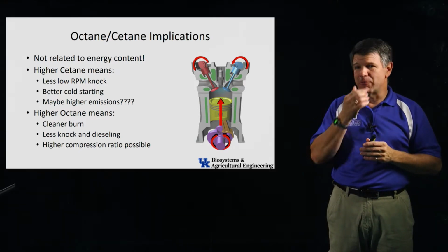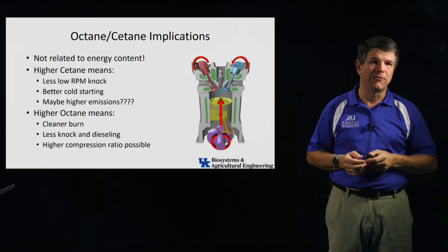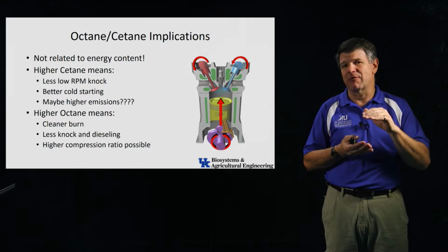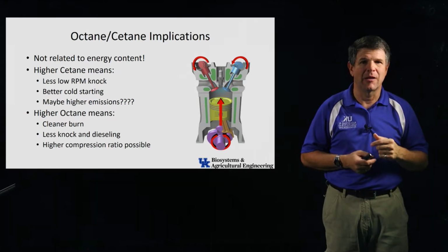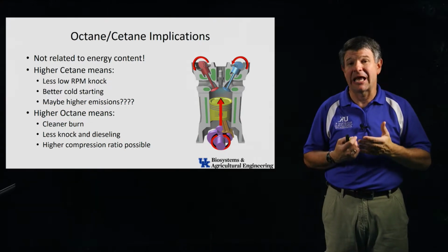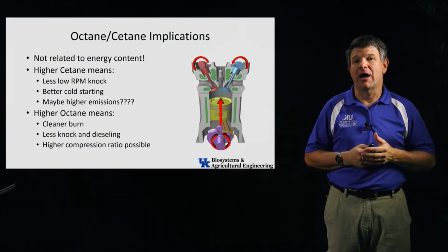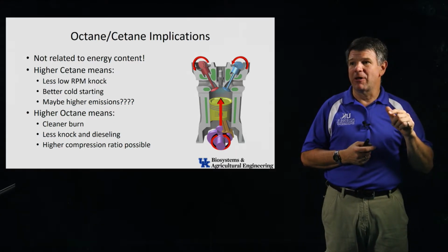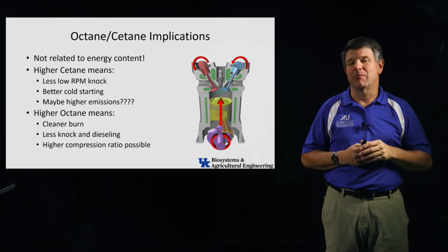All right, if it runs well on a low octane fuel. And that's the key, okay? If it's got a low enough compression ratio, it's not dieseling, it's not hammering, it's not knocking, and stuff like that, use a low octane fuel. Again, you're not getting any more energy content out of the high octane fuels. If your engine doesn't run well on it, maybe the manufacturer has a higher compression ratio.